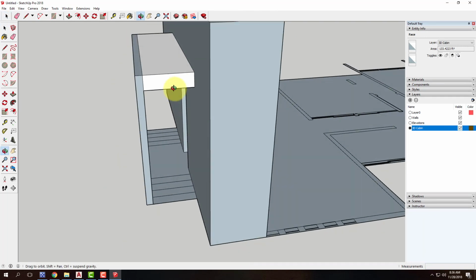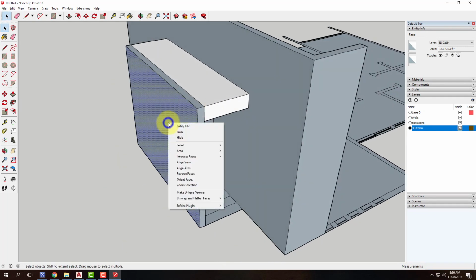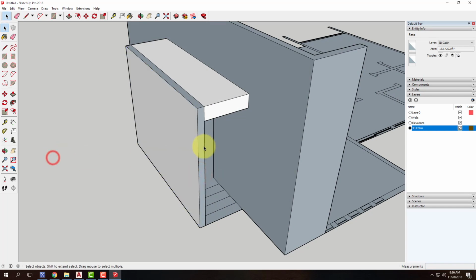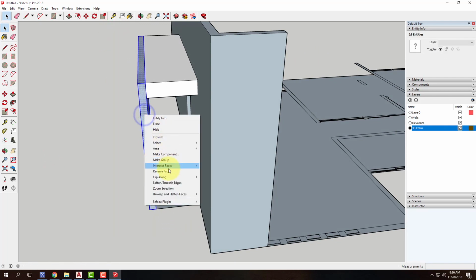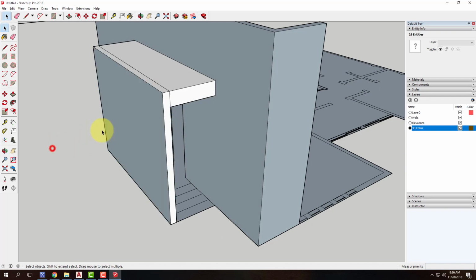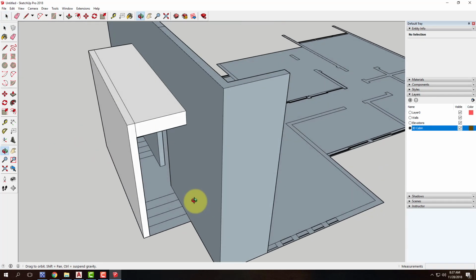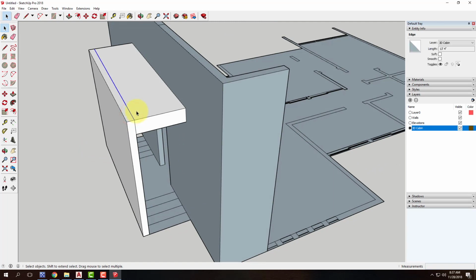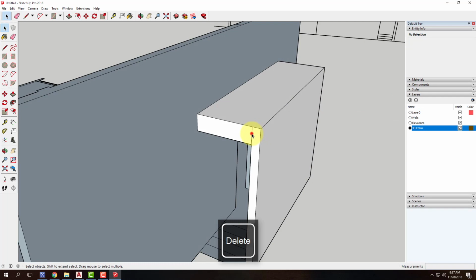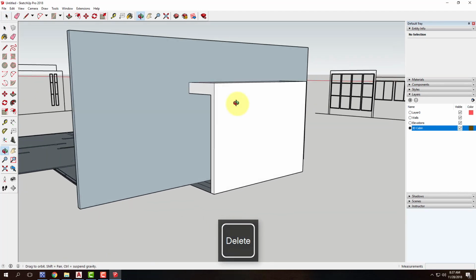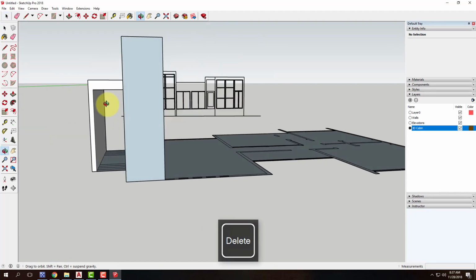If you're worried about it, you can select these objects, right-click, and say Reverse Faces. And it'll turn to the whitish color. So I could take all of those, for example, right-click and say Reverse Faces, and that would all be the white color. I can go in afterward and delete this, and delete that, and delete that. And suddenly I've created that part of my entry.